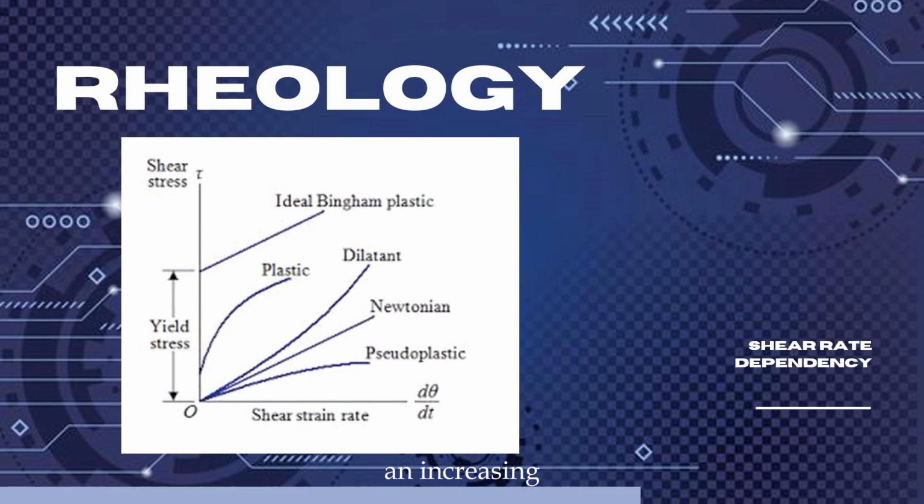Pseudoplastic: in this type of flow an increasing shear force gives a more than proportional increase in shear rate, but the curve begins at the origin. One of the examples is salad dressing. Dilatant: the shear stress-shear rate plot of this type of flow begins at the origin but is characterized by equal increments in shear stress giving less than equal increment in the shear rate, such as raw starch suspensions and syrups.